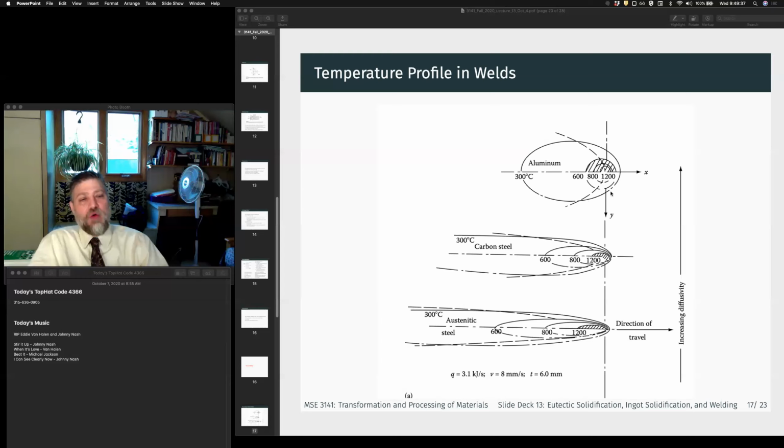We've got a weld pool that, depending on the heat conduction in the metal, is going to be more or less ellipsoidal on the surface, or more spherical, as our diffusivity and heat flux or heat transfer go up. And so the region of the melt pool is actually really complicated. We've got a melt pool that's traversing. We've got a thermal gradient from the top to the bottom.